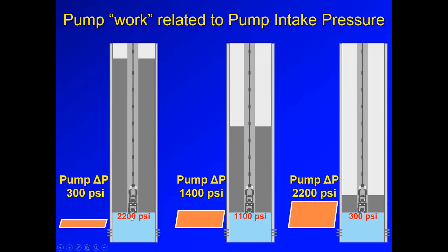And if you think about that, the pump is actually providing the additional help to lift the fluids from the fluid level to surface. How does that work? Well, imagine you don't have any rods or pump in this well and you have only tubing. If there is nothing blocking the tubing intake or providing any assistance, the same reservoir pressure that is lifting the fluids up to this fluid level height inside the annulus would lift the fluid to this point inside the tubing as well. So it would be equalized by communication at the bottom of the tubing. Even without any pump, the tubing will be full up to the fluid level height. Then if you install the pump, the additional help would be lifting the fluid from the fluid level top to surface. That's another way to see what the pump is doing for the system.